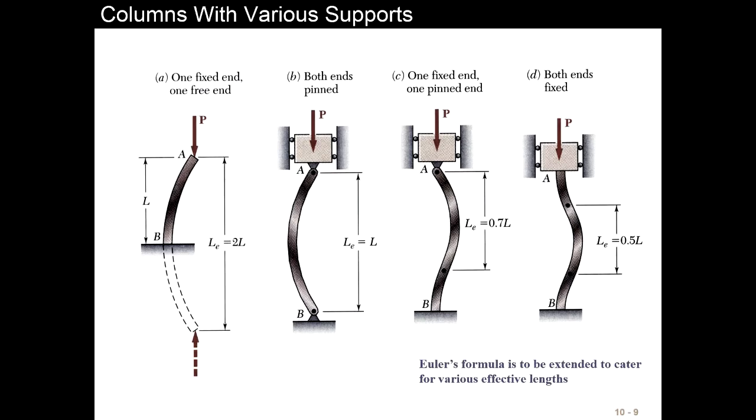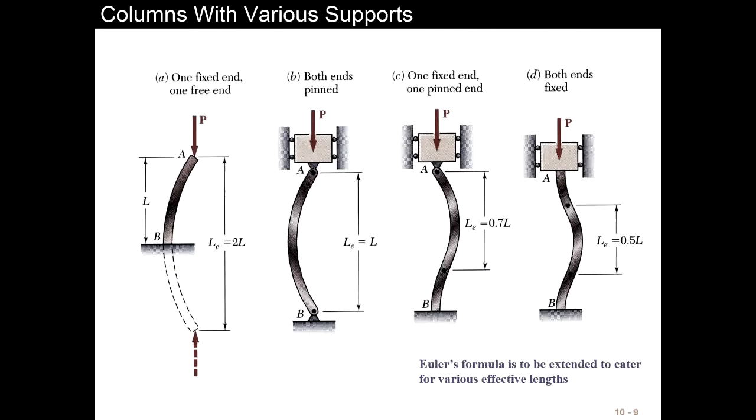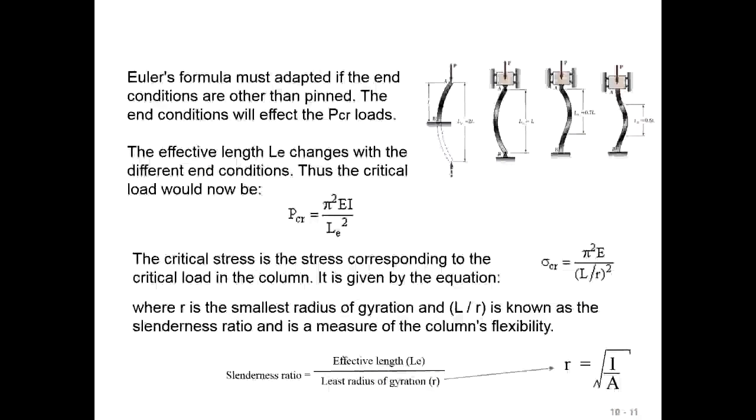Now this is like the theory for structural mechanics, and I know I haven't put it in. Like I've got some notes here. Like when you come to do some design next year, you'll see how they take that theory into the design of steel columns or concrete columns, and how they use these factors depending on the type of material that you have. Like steel is usually pinned and sort of fixed at the bottom. Concrete is always fixed either side. So as far as you're concerned, you need to know all of them.